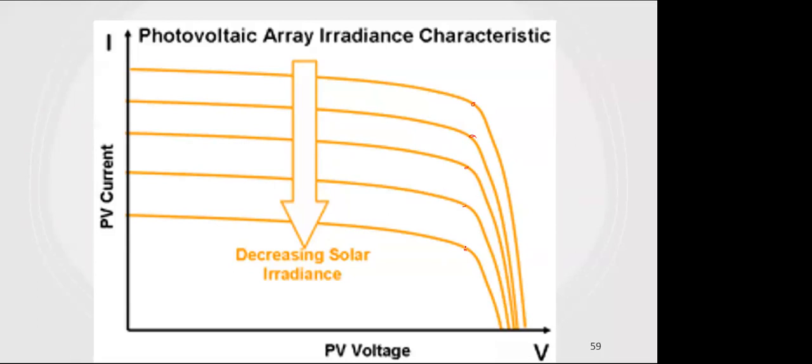If the solar panel is fixed in one place, we cannot say it receives constant solar irradiance. The solar radiation varies with the time of day, the time of year, and atmospheric conditions like cloud cover and other things. That is where maximum power point trackers come in. They are very important. Otherwise, you cannot harness the maximum amount of energy which can be generated by the photovoltaic.